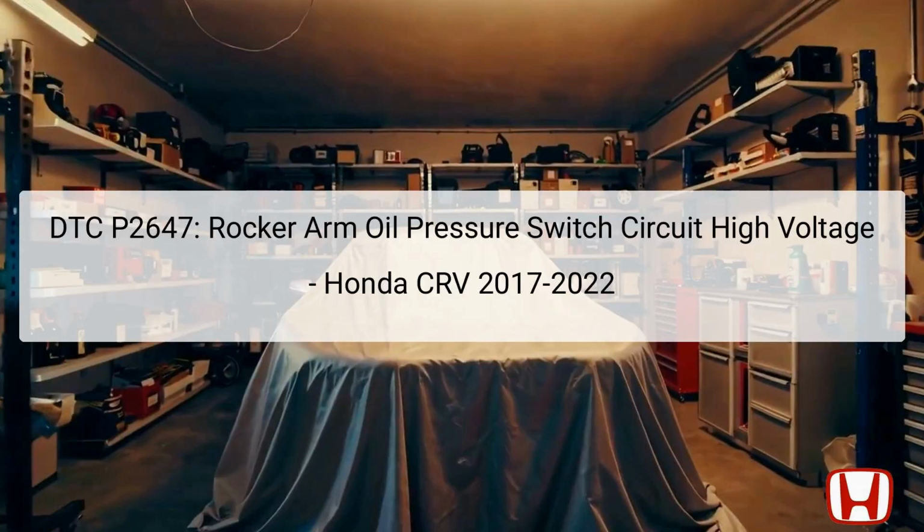The Diagnostic Trouble Code, DTC P2647, pertains to the rocker arm oil pressure switch circuit, high voltage, specifically for the Honda CRV models from 2017 to 2022. This fault indicates an issue with the oil pressure switch, which directly affects the variable valve timing and lift electronic control (VTEC) system. The VTEC system is crucial for optimizing engine performance by adjusting valve lift based on engine conditions.